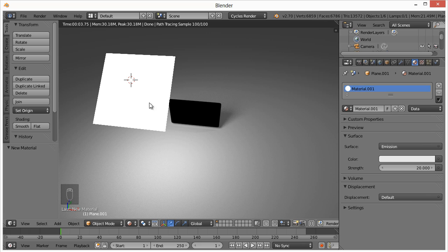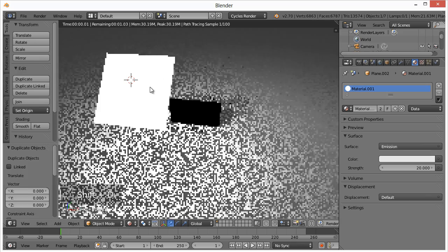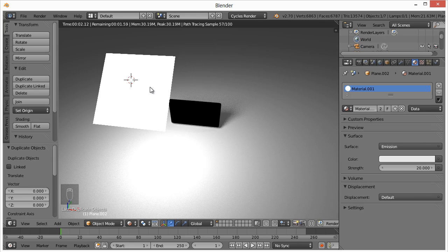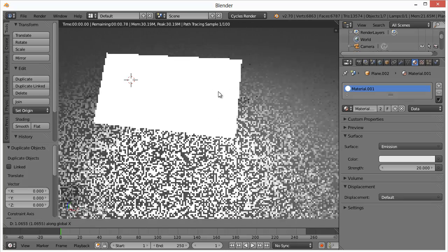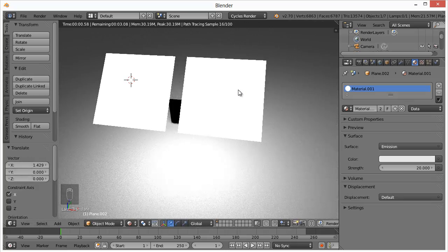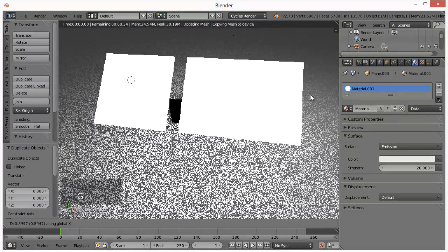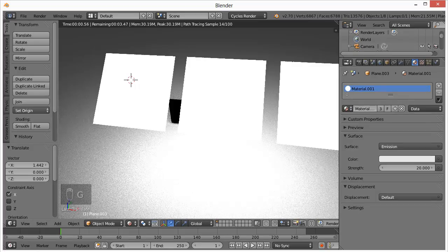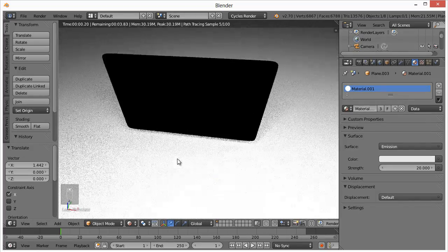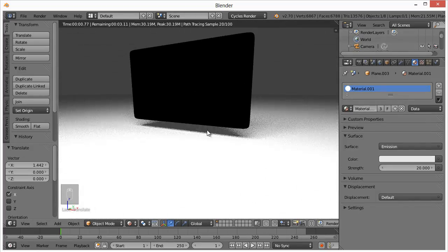All right, so when you're in rendered mode, you can't see what you're selected on, but you could still work with objects. So if you hit Shift D, enter, and then hit G, and that's the shortcut for move, X, so G and X, and then move your mouse, and then Shift D, enter, G, and X. Yeah, right around there will do well.